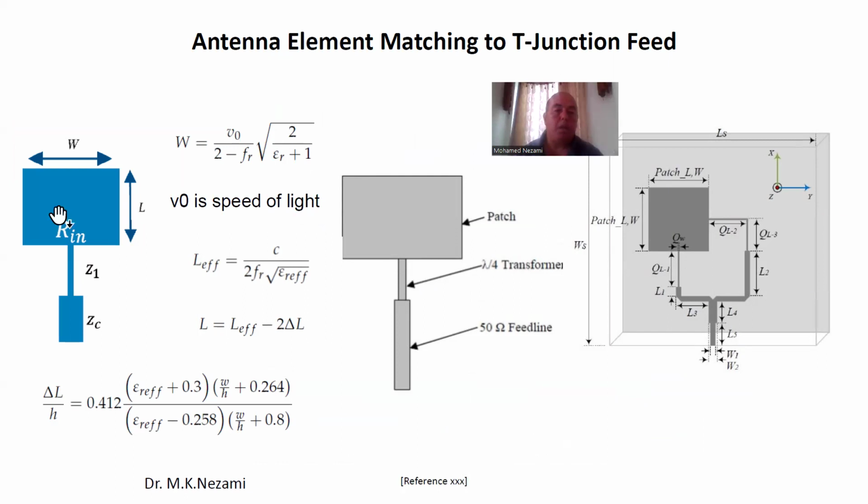So, showing you the linear and the circular polarized, the impedance in here, basically you need to transform it to the main feed line of the antenna array feeder. So you have control over this, and this is just showing you how simple it is to come up with the dimensions of an array with a single unit cell.